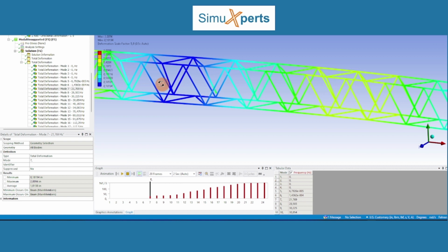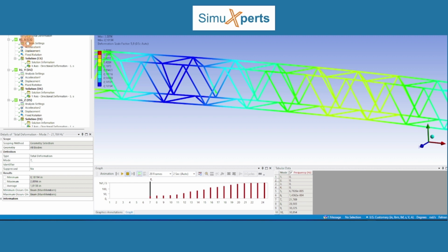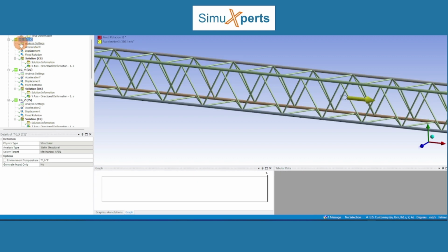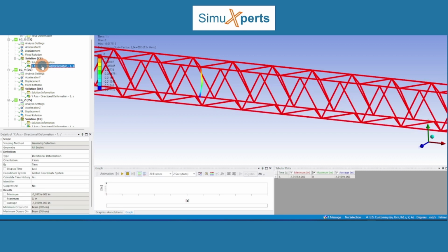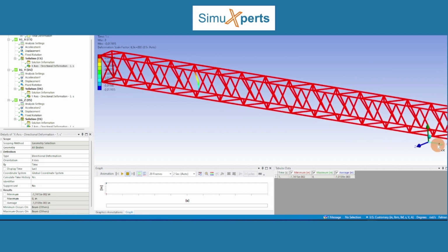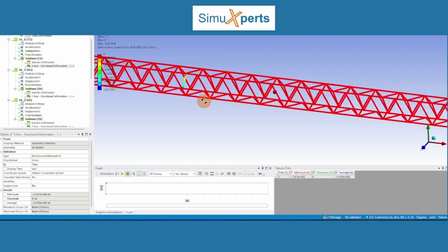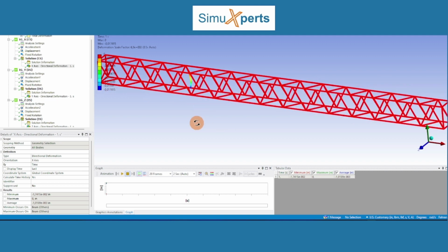What else can we do to detect such a condition? What I really like to do is to apply a 1G static loading in each direction. So here is 1G applied in X, and then I looked at the displacement in that direction. That's this result right here. And as you can expect, if you apply 1G in the X direction with the beam being simply supported at each end, notice now that I do have the boundary conditions. Of course, you cannot do a static analysis unless you've got some boundary conditions. You can easily see that right away, this solution allows you to detect that this member is disconnected.